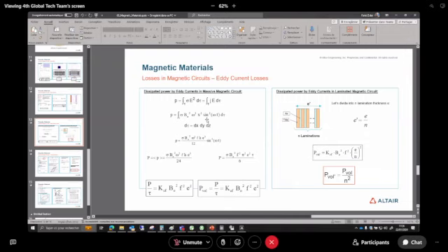Then it will have an impact for sure on the BH curve. So there is a compromise to find according to the mechanical limit and the impact on the BH curve. So this is really clearly where we can see the impact and the usefulness of the lamination. So this is one part of the iron losses.